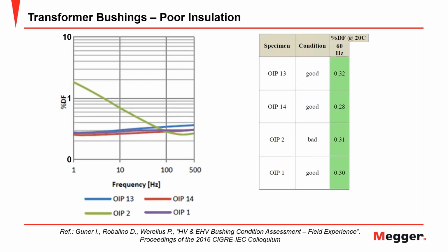Now, let's look at this condition, because a work that was presented about 3 or 4 years ago for Cigre was based on the correlation of power factor, narrow band, and dielectric frequency response on the analysis of OIP bushings with respect to DGA. So I really invite you guys to look into this reference. If you need the link, we can provide the link so you can have a little bit more information on that correlation between these frequency response techniques and DGA.